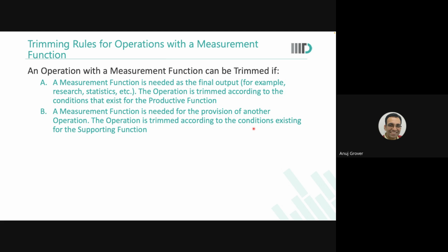Earlier, what was required to be done? In the earlier process, the heating would be happening through some method, and there was always a temperature that would be measured. And sometimes you are quenching it at 71 degrees, sometimes at 70 degrees, sometimes at 69 degrees. So there was always this variation. But now, by using a scientific principle of Curie point, Curie temperature, the need was eliminated in itself. So the measurement is no longer required. Are you able to see this?